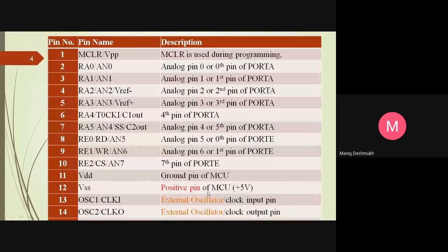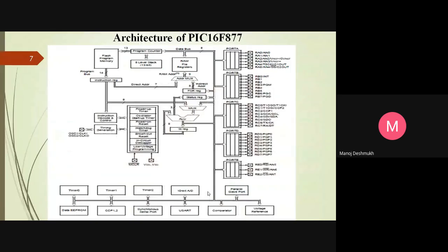Based on that, if we consider our architectural diagram of the PIC16F877, consider that you have 5 ports, that is A, B, C, D and E. Keep in mind that the number of pins available is 6 for port A, 8 for port B, 8 for port C, 8 for port D and 3 pins for port E. Now draw an L section like this, a reverse L, or simply a right angle section, from the top right to the bottom, and again from the bottom a straight line.